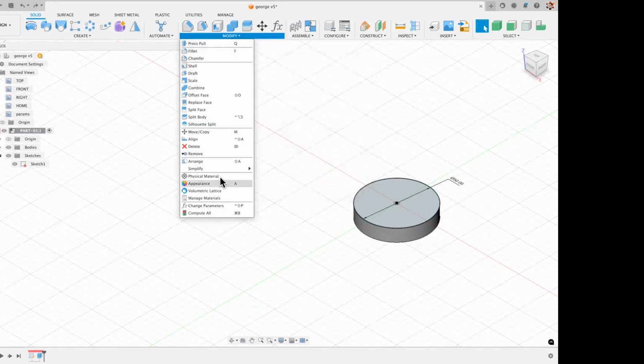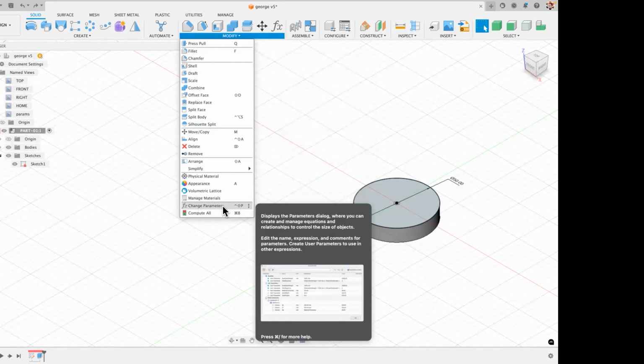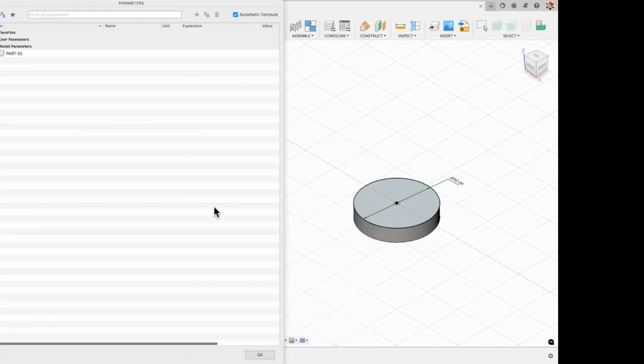Okay. All right. So now we're going to go into a table where all of these parameters live. And you can be very efficient inside this table. So up at the top center, we have the modify menu. The drop down menu modify, and we're going to come all the way down near the bottom. It says change parameters, little FX change parameters. And make yours here on the left side of the screen, whatever you have to do to resize it, so we can see this at the same time as we see that.